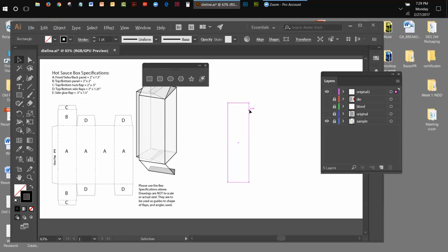Yeah, you're right. I'm going to hold down the Shift key at the same time, and I'm going to drag out. Now, you see I have my smart guides going, guys? Can you see that there's a line that runs through it and it says intersect? Yes. Okay, that means basically that my lines are intersecting one another. I've moved it to the point of intersection, which means that they are basically sitting one on top of each other. And I'm doing that on purpose. I want them to slightly overlap each other for a later step. So you understand? Yes. Any questions?